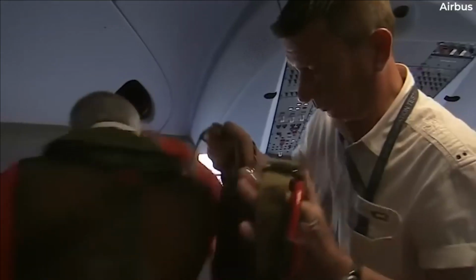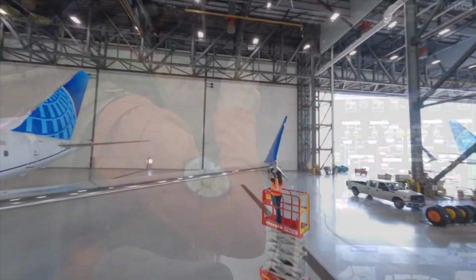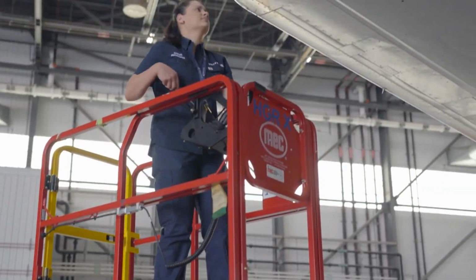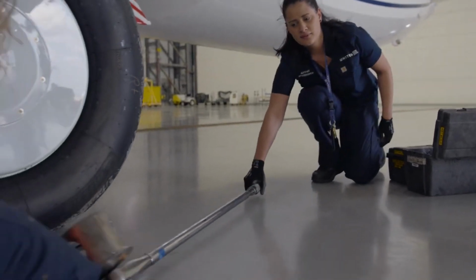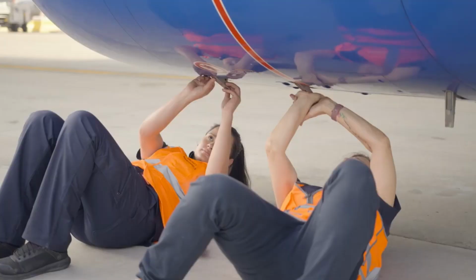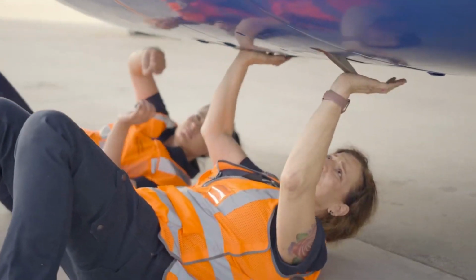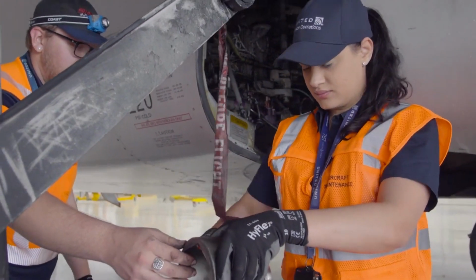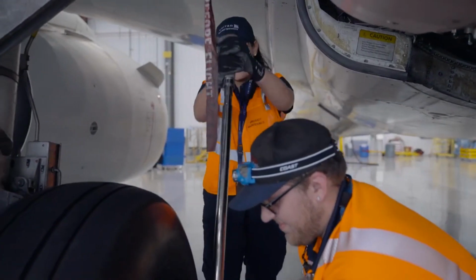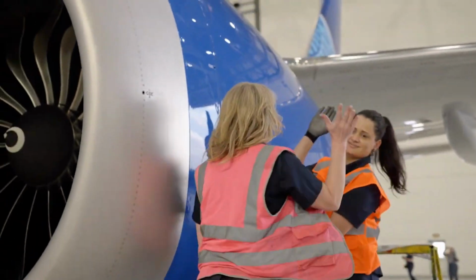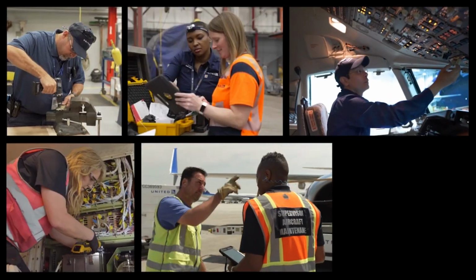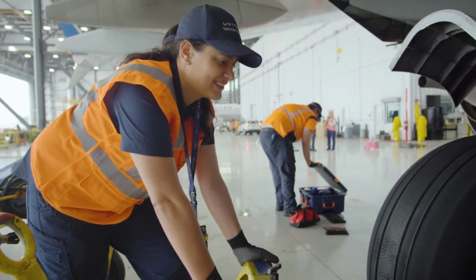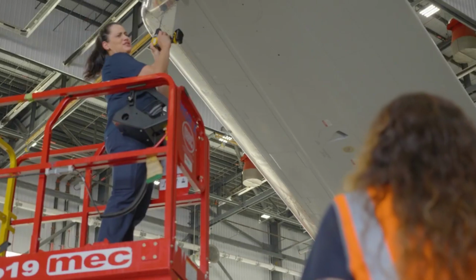14 CFR Part 145 Repair Stations. This regulation underwent a major rewrite released in 2004 and was the most comprehensive change in nearly 20 years. It may be of interest to note an airframe and power plant (A&P) certificate is not necessary to be employed at a repair station. The repair station may also employ both repairmen, under 14 CFR Part 65, Subpart E, and non-FAA certificated personnel. All work that is signed off is done so using the repair station certificate number and must be done only by persons authorized by 14 CFR Part 65 to approve an article for return to service, RTS.